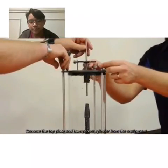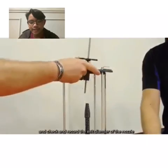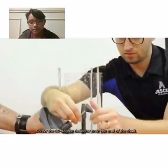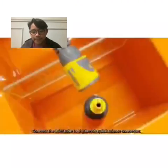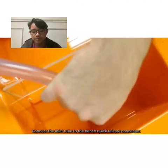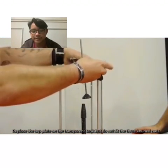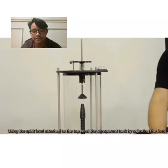Remove the top plate and transparent cylinder from the equipment and check and record the exit diameter of the nozzle. Screw on the 90-degree deflector. Connect the inlet tube to the bench quick release connector. Replace the top plate on the transparent tank but do not fit the 3 knurled nuts.